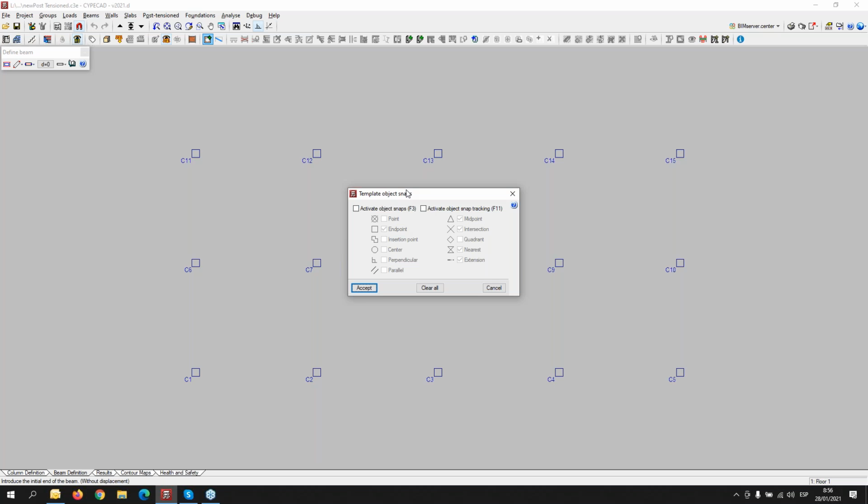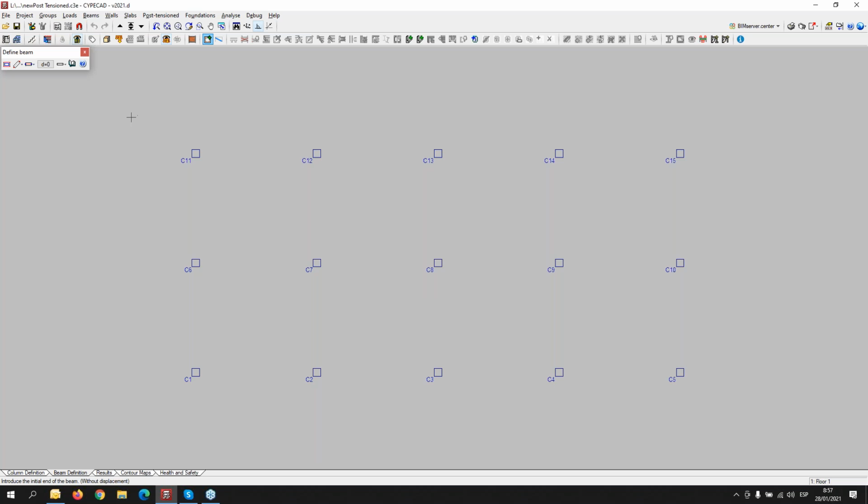And I think that we have some different videos in our YouTube channel with different webinars or demos that demonstrate that. And in this case, for our example, I will use the columns as reference. So to obtain the position of a beam, in this case a limit beam, I will approach the first column, C1.